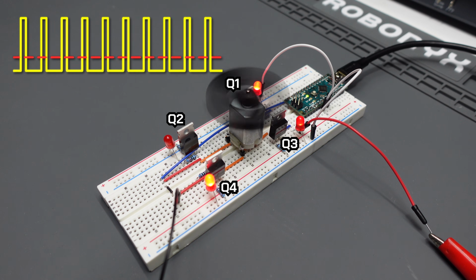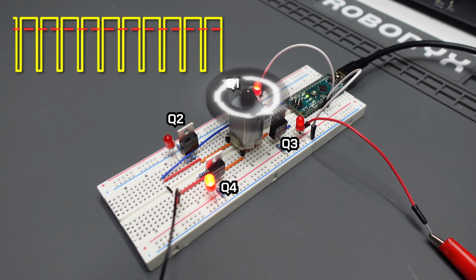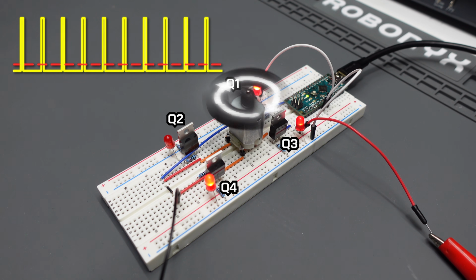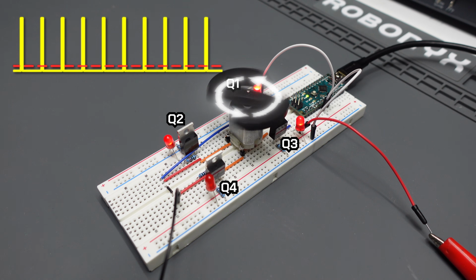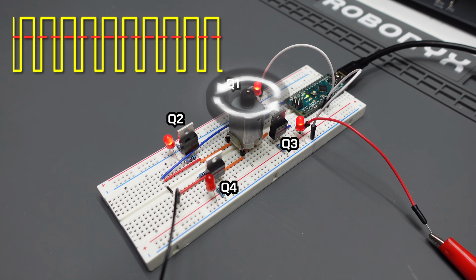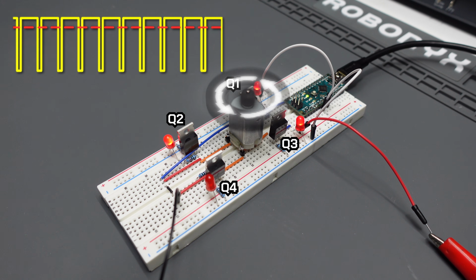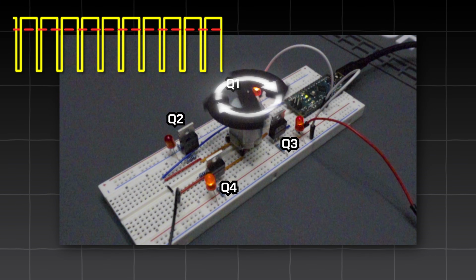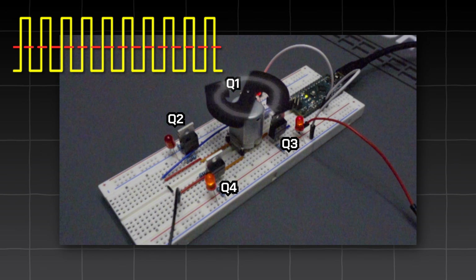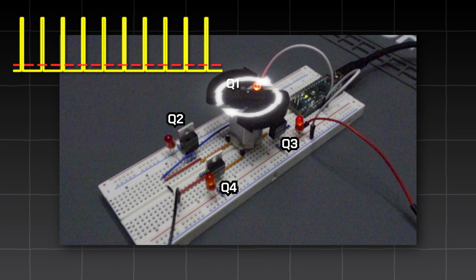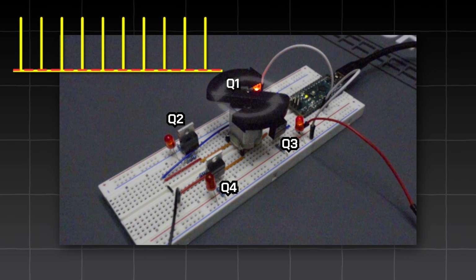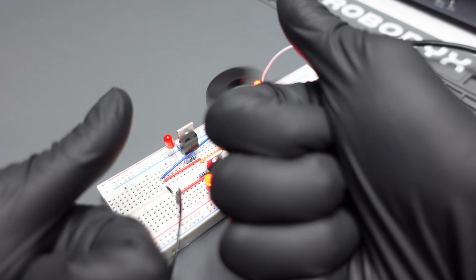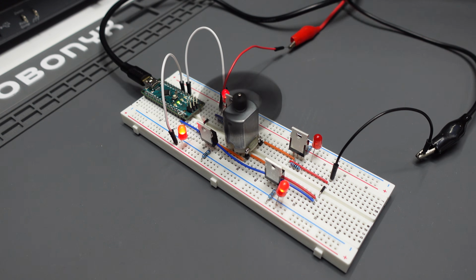Here is the same signal but connected to the Q1 and Q4 gates, and as you can see, it's gradually slowing down. Now, by using the H-bridge and applying the signal to Q2 and Q3 gates, we can switch the direction and use PWM to gradually speed it up in the other direction. Now let's slow-mo this footage too because you can't really see the direction it's spinning in because it's so fast. As you can see, it spins one way, then slows to a stop, then slowly ramps up in the other direction. Let's freaking go!